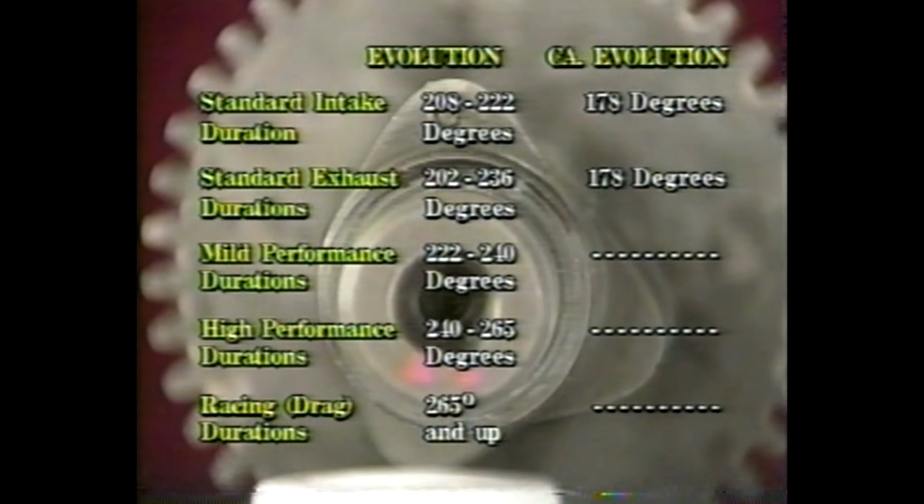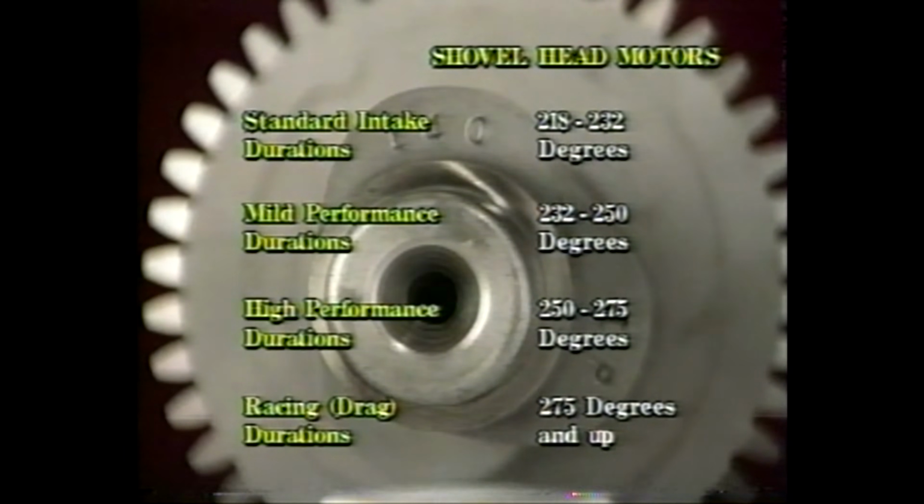As we can see from this diagram, the standard intake duration for a stock 80 cubic inch Evolution motor is between 208 and 222 degrees, and the stock exhaust duration is between 202 and 236 degrees. Now, if we have a stock California 80 cubic inch Evolution motor, both the intake and exhaust durations would be approximately 178 degrees. In contrast, a high-performance camshaft would have durations between 240 and 265 degrees. Any duration above 265 degrees we would associate with a racing or ultra-high performance camshaft.